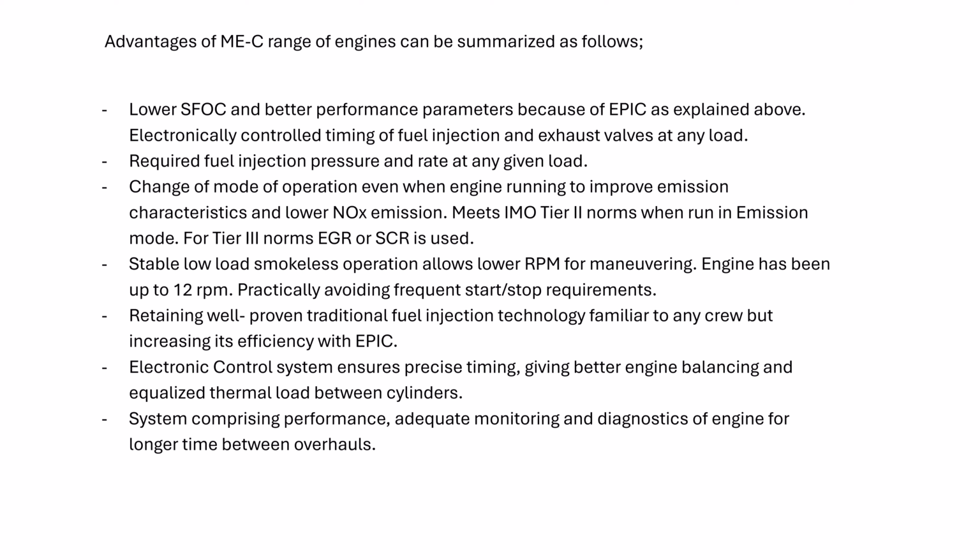Retaining well-proven traditional fuel injection technology, that is the same for the MCC engine also. Engineers are well familiar with that. But increasing efficiency with EPIC control. The electronic control system ensures precise timing, giving better engine balancing and equalized thermal load between cylinders. The system comprises performance, adequate monitoring, and diagnostics of the engine for longer time between overhauls.